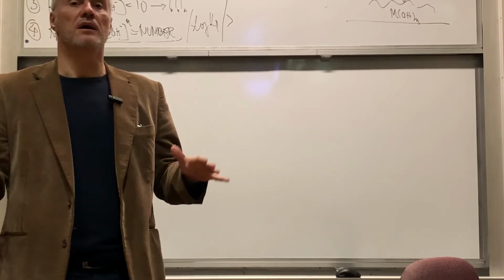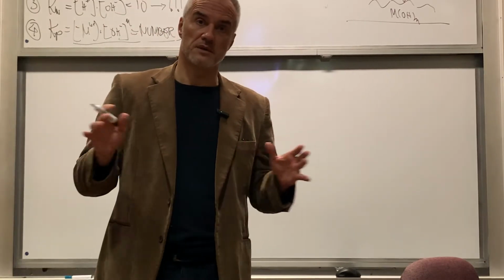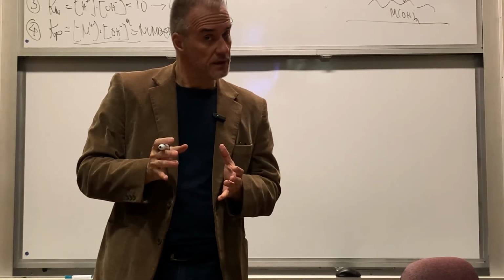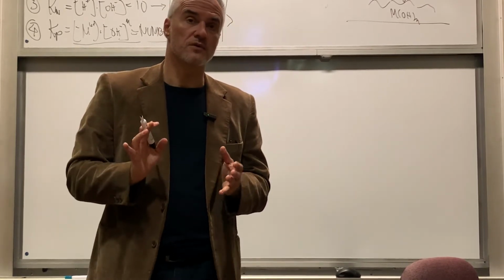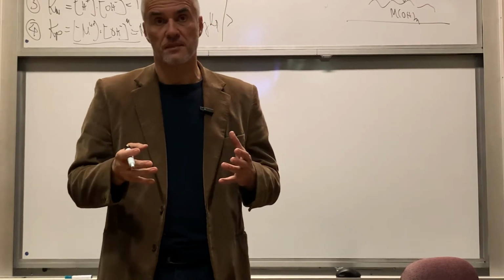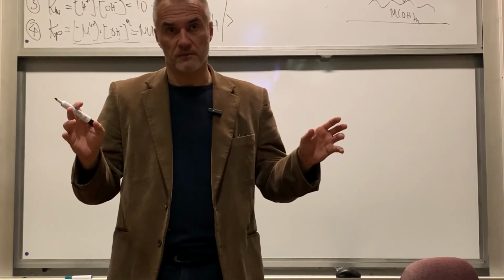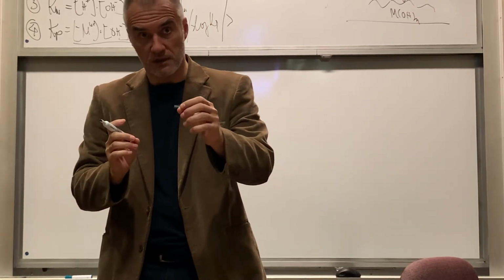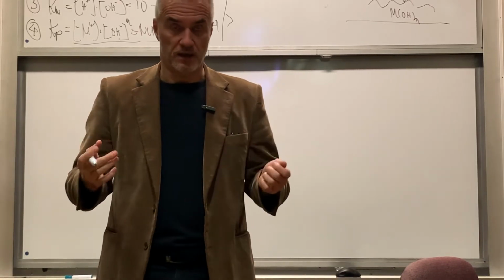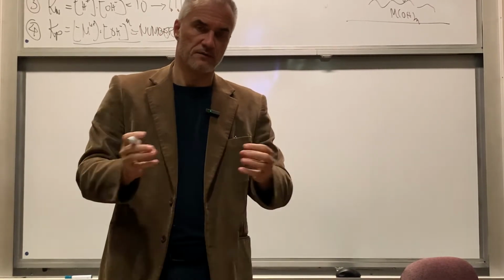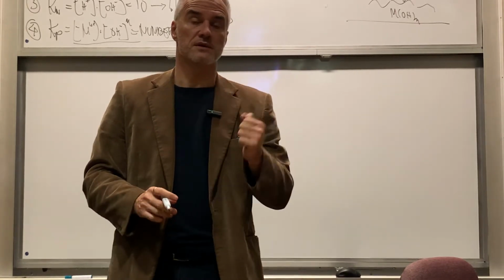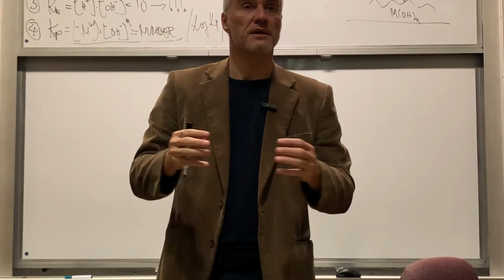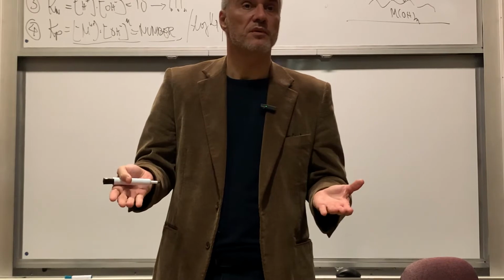For example, if you're talking about magnetic materials, the saturation magnetization for the metal phase is 2.4 Tesla, for the oxide phase it is probably 0. Now, for the volume of the film, that means your magnetic moment will be diluted by the percentage of the phase that is oxide you have in there. And you think you're generating a film in a device that's supposed to do the job at 2.4 Tesla magnetization, but actually the real magnetization in that volume of magnetic material in our device is maybe 1.6.